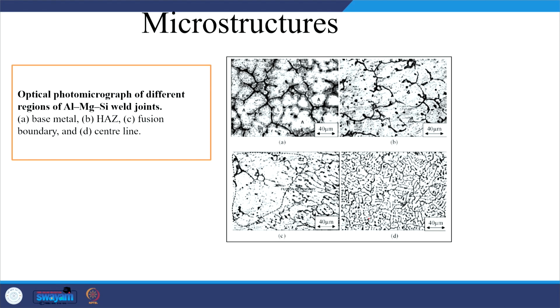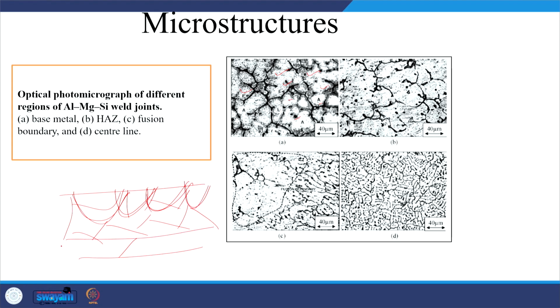Here we see the as-cast aluminum magnesium alloy, which shows a very coarse grain structure. You can see these grains are extremely coarse. When we perform the TIG remelting, say this is the surface, and here we have a very coarse structure like this, we are melting up to a certain depth. Whatever depth is melted, that zone will be refined certainly, but all the zones which experience the heat will get coarsened. So, a coarse-grained HAZ is produced. That is what we see.